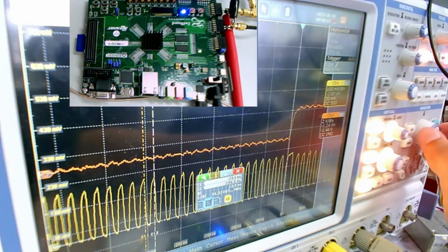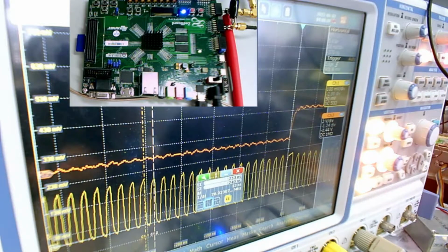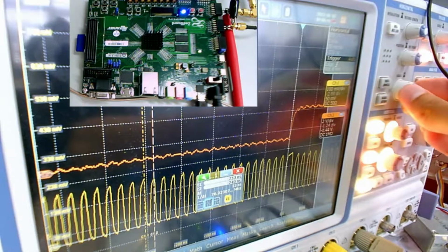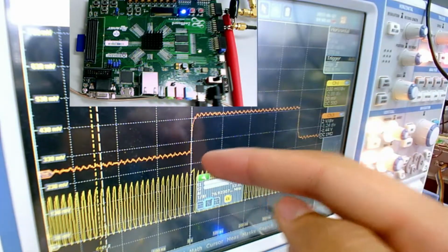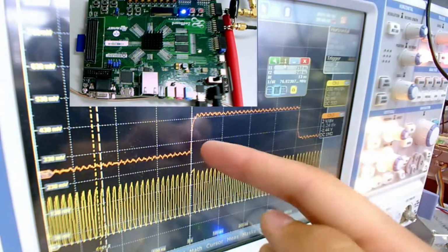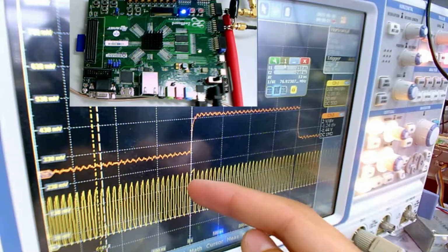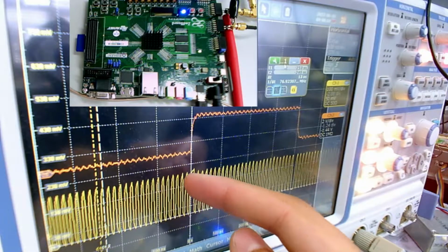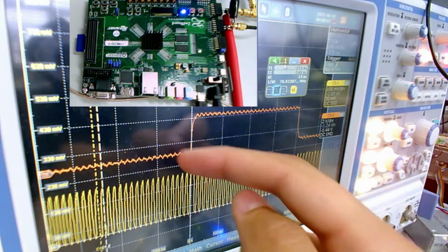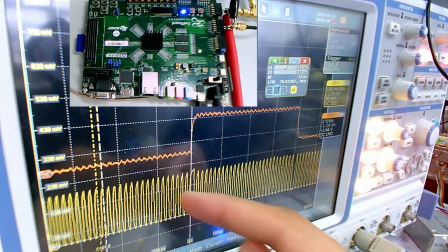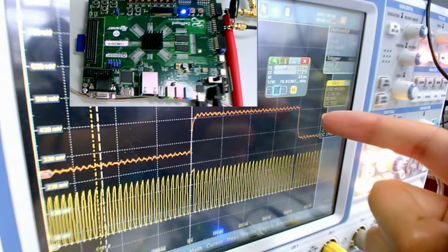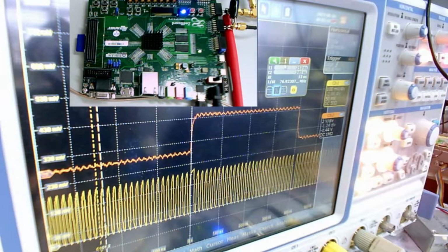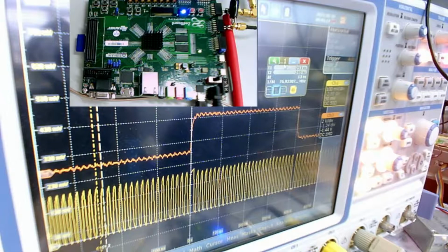Its frequency seems to be around 70 megahertz, and every time you see a change in the PRN here, the shift happens and the phase changes. So here it goes up, and instead of having a higher and lower state, you have twice the higher state and then the lower state. And here, when the PRN is going down, the phase, instead of going down then up, stays down for a period.